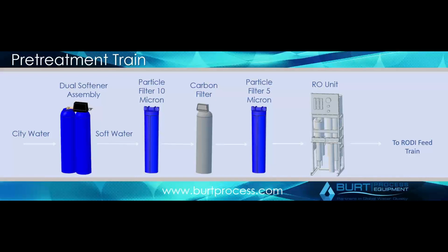So water softening is definitely one of the big ones that you want to look at as part of any pretreatment train, which is also why it's very important to have an understanding of what your incoming water quality is. You can see what your hardness level is, what your chloride level is, because things like chlorine or chloramines, which are byproducts of city water treatment, are put in the water as disinfectant. When you concentrate that chlorine, you can actually oxidize your RO membranes, which is another reason why the carbon filter or some other means of reducing that oxidation potential of your water becomes very important.